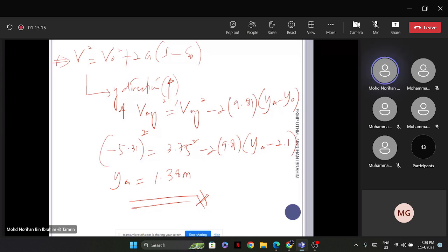The only difference between the first and the second one is how we fix the positive sign convention and fix the origin of this free body diagram, origin O, where I fix it on the ground for this one. So we can directly find out what is YA.